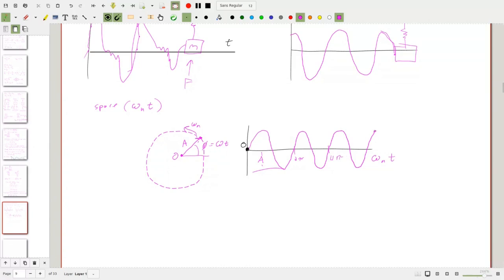And then whatever point you're at, right, you can start to see that you can get the amplitude or the distance x of whatever point you're at is a sine omega nt. Right, and this is just kind of a visualization in this omega nt space. But the core idea here is that we're just rotating around a circle, and that's how we get our simple harmonic motion, right? So it's always going to be sinusoidal because we're always rotating around a circle.